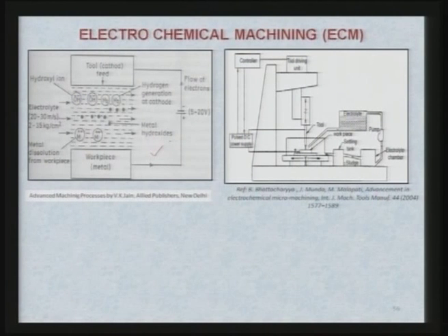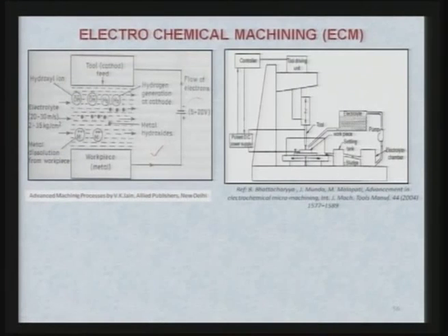Now, this is for macro electrochemical machining, but for micro electrochemical machining you have to lower the voltage which you are using over here, and this is the setup shown over here, developed for electrochemical micro machining by Bhattacharya et al. at Jadavpur University.